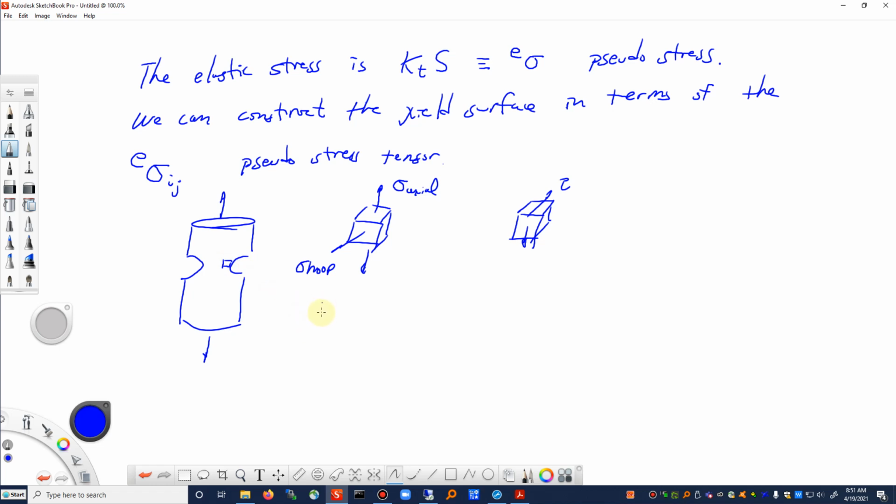We've talked already about this idea of linear superposition. If I have multiple loads, say maybe this is tension and torsion, with a load time history of my tension and my torsion, I don't need to do an entire finite element analysis of those two time histories of load if linear superposition applies.